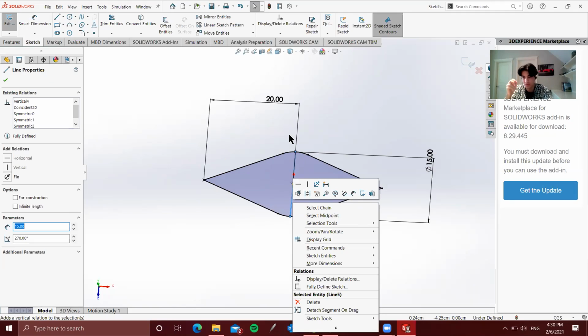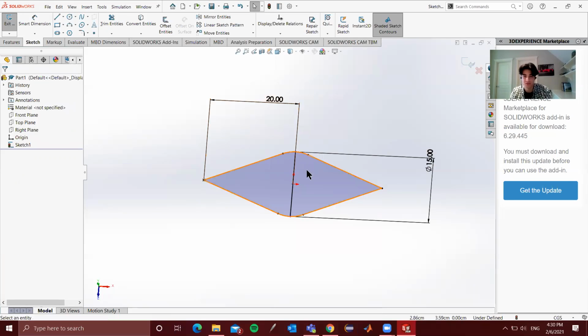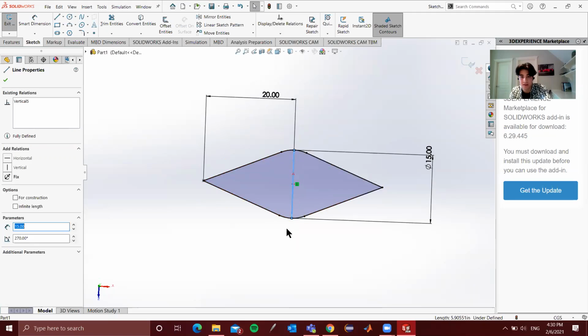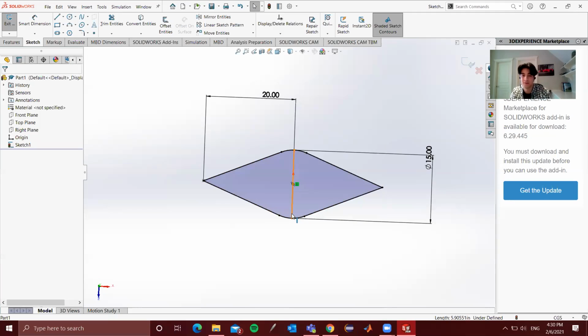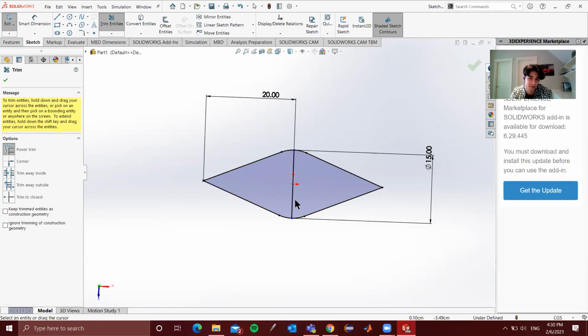So essentially SolidWorks will see this and consider it to be part of the sketch that you're trying to create. But if you convert it to a construction geometry, essentially it's invisible, if that makes sense. So this is a useful thing to do, but for the purpose of this, I'm just going to get rid of it. Sorry for the confusion there.